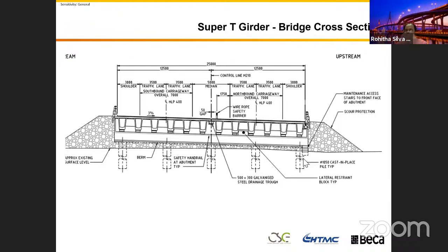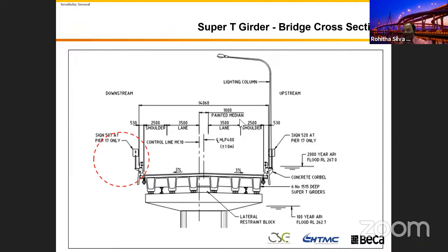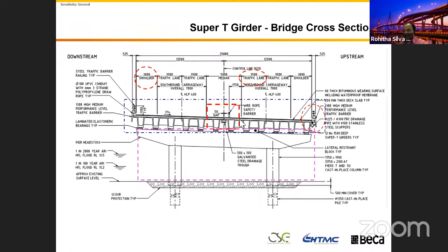But beyond the bridge, you have a road that is just built on a fill. Behind the bridge, we just fill. We have to fill that 4 meters. Then we have to batter this one down. We're going to learn that in here. Just to show you, at different locations of the bridge you have different cross sections. There are different forms as well.